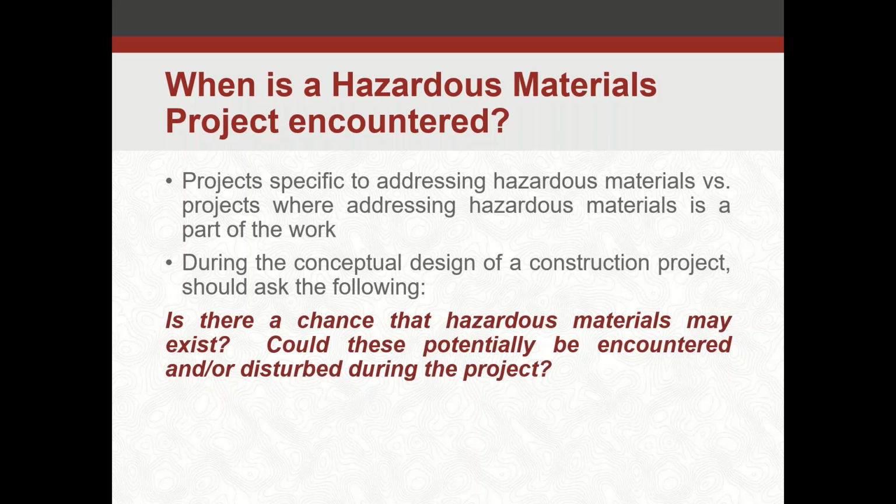Regulations dictate that when you do a renovation, repair, or any sort of work that may impact suspect asbestos contaminated materials in a building, you have to do the survey, assessment, and abatement of that material before you can continue on with other work activities. So a lot of times when you are dealing with work inside a building, there is a requirement to make sure you don't have those types of materials before you proceed with the work as a general construction or demolition type project.